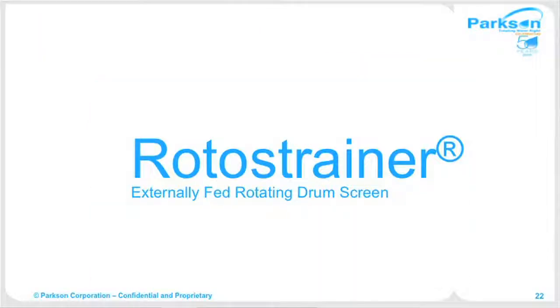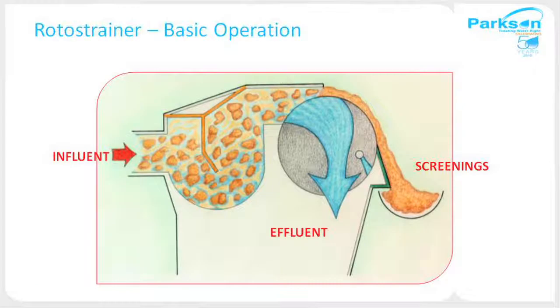Our next screen that we're going to discuss is the Rotostrainer. It's called an externally fed rotating drum screen. The operation of the screen is basically that the influent comes from the back end again and fills up the head box, and we have a U-shaped head box there. You see the baffle again in the middle, which slows down the water coming into the screen and permits it to evenly go over the round screen cylinder.